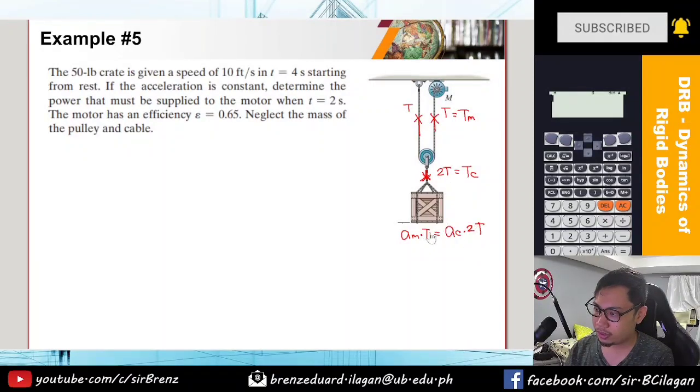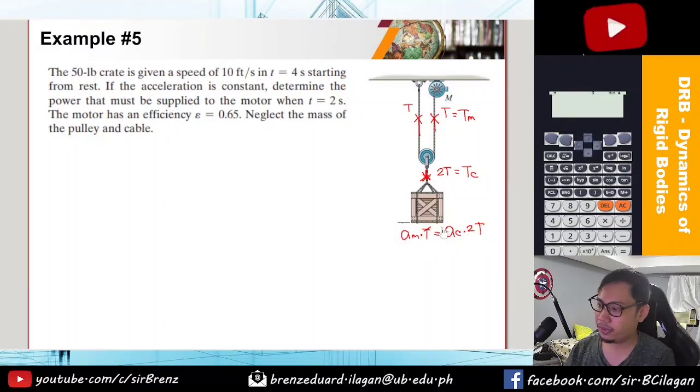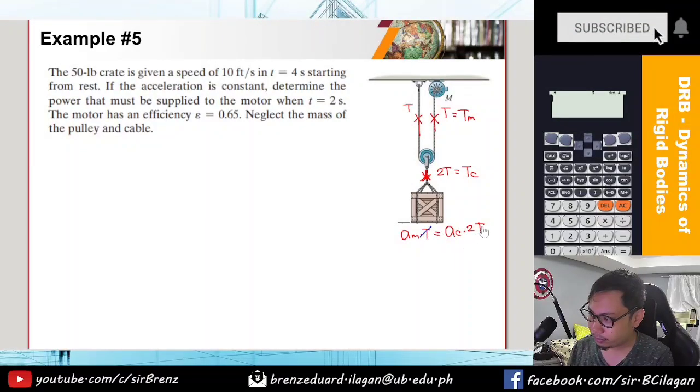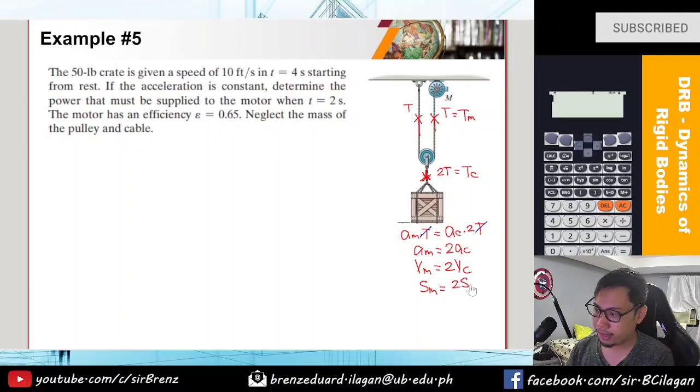We can cancel out this T. Therefore, the acceleration of the motor, A sub M, is just equal to 2 A sub C. Likewise, the velocity of M is equal to 2 V sub C, and the displacement of M is equal to 2 S sub C.